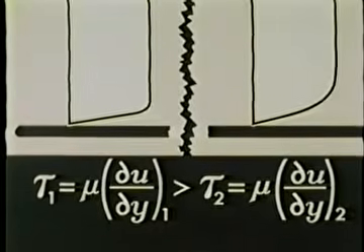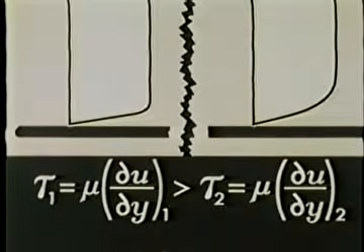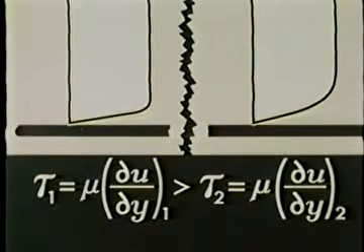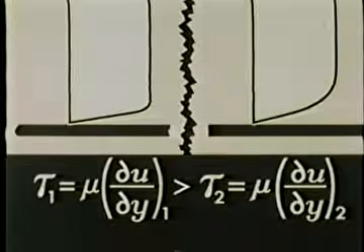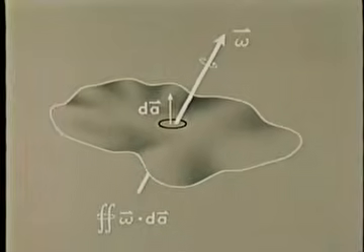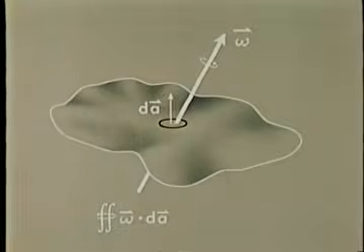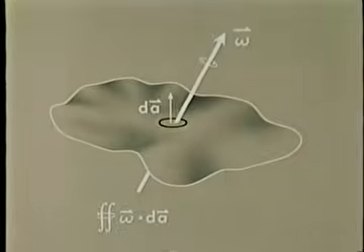The growth of the boundary layer thickness along the plate can be explained by considering the time history of the vorticity within the boundary layer. Stokes Theorem states that the area integral of the vorticity omega, bounded by a closed contour, is equal to the line integral of the velocity around the bounding contour.